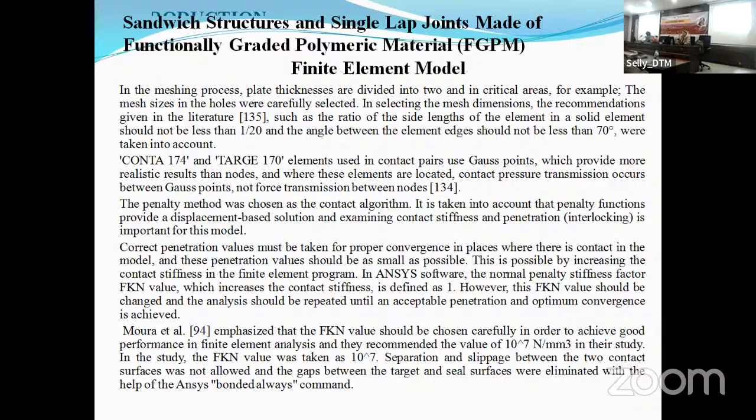Transmission occurs between all the Gauss points, not transmission of the node. Generally, ANSYS uses load transmission by its own nodes, but here we will use Gauss points. It's important. And we take into consideration some interlocking and some restrictions of the dead points.